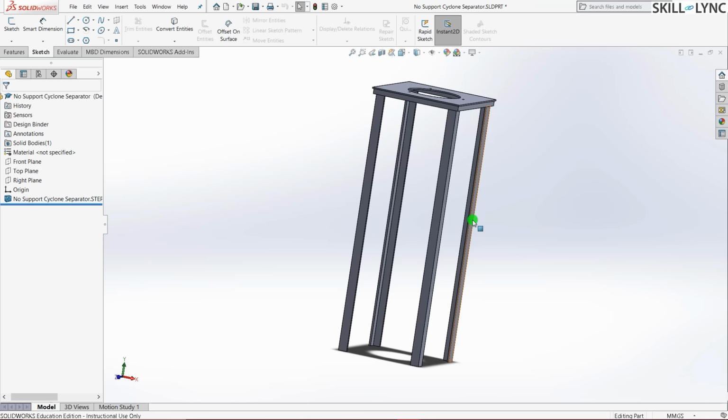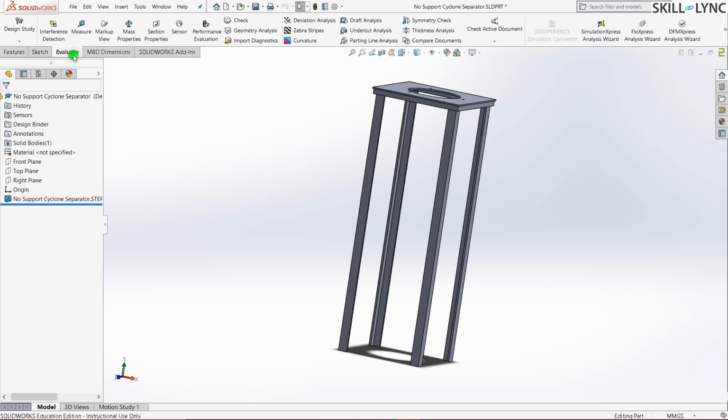And that's it. Once you create your stiffener, apply loads from the top part, notice how much buckling factor of safety you're getting, and then go to Evaluate and run a design study on this. Similar to how I did it in the previous example, just create your stiffener and run a design study based on the position of your stiffener. You will get different buckling factors of safety for different positions of the stiffener. Find the most optimal position and submit it.